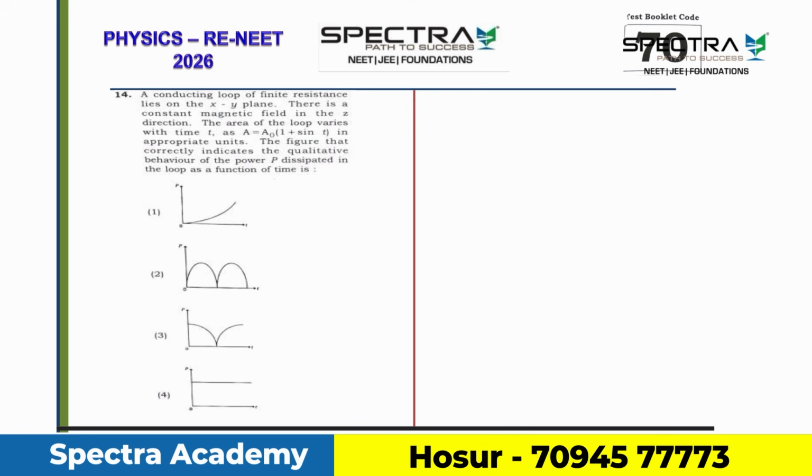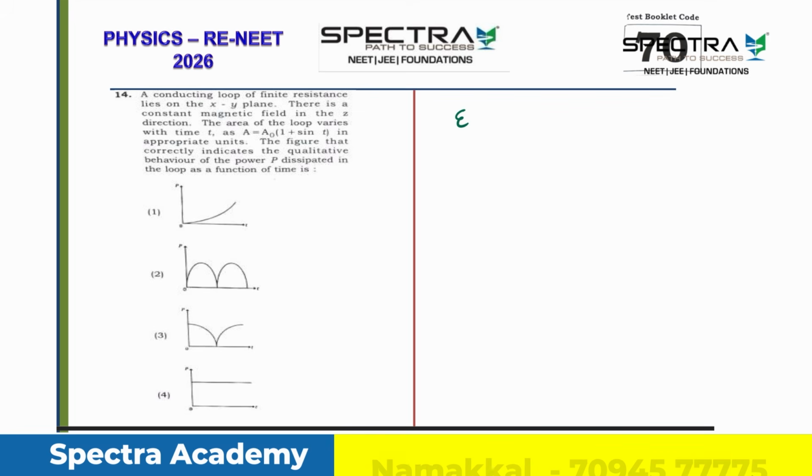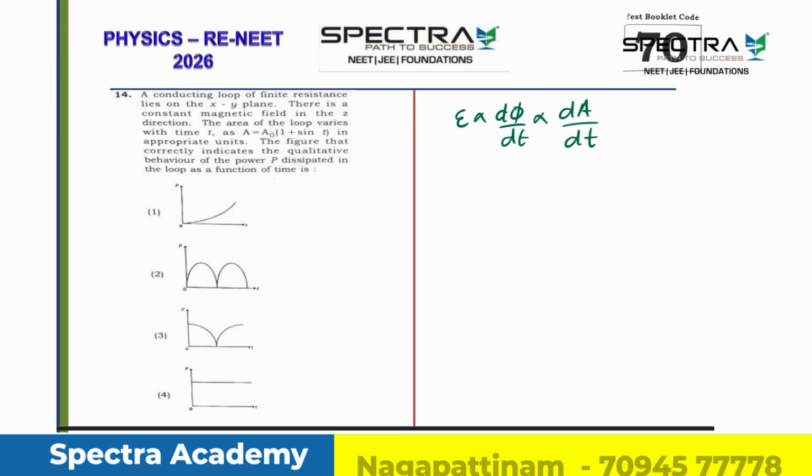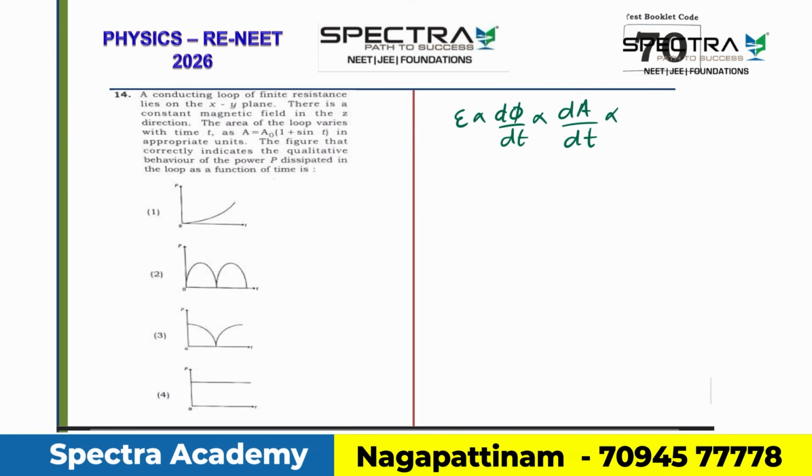So it is very clear that the induced EMF is due to the changing area. Induced EMF is directly proportional to d phi by dt. Since the magnetic field is constant, this is directly proportional to dA by dt. So what is dA by dt?